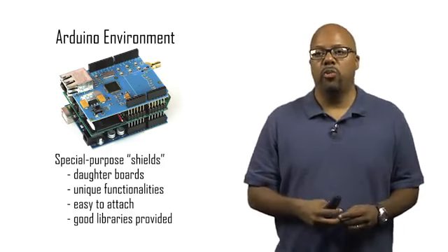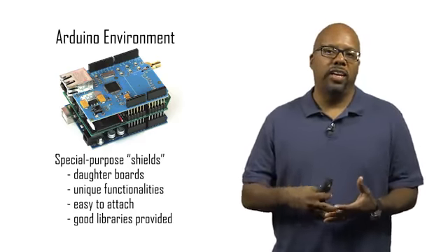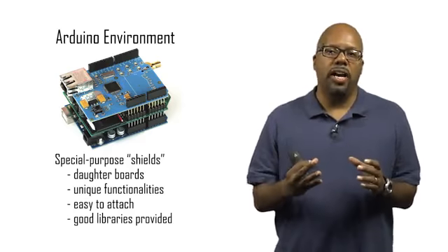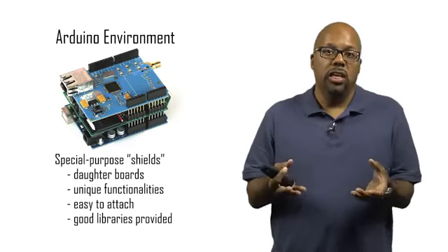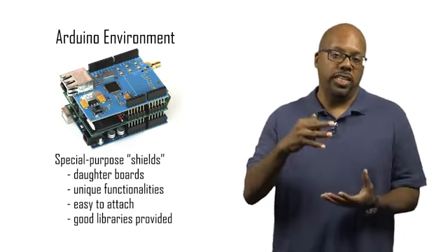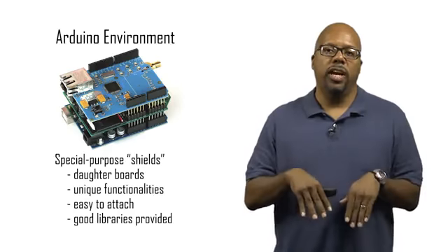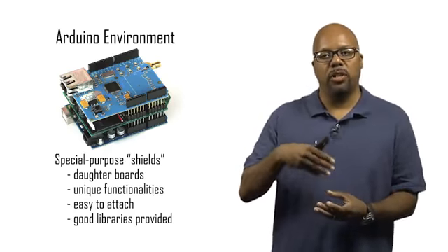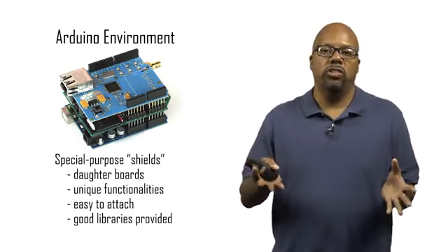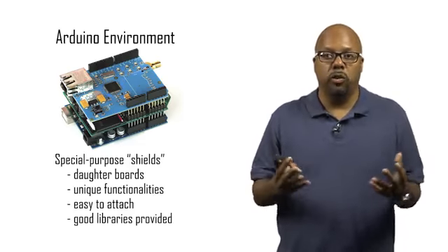The thing looks like it has 80 pins on the side. You got to wire all that up. It's a lot of wiring, and it's a lot of coding. But what happens with these shields is they basically pre-wire everything. So they give you a board, a little shield, which has the chip on there pre-wired. You take that board, you stack it on top of the Arduino. So it has pins going out underneath the board, and you stack it on top, it goes into the holes in the Arduino board. So it is immediately just wired for you to the Arduino. You don't have to do any work, all right? You don't have to have any knowledge about the wiring.